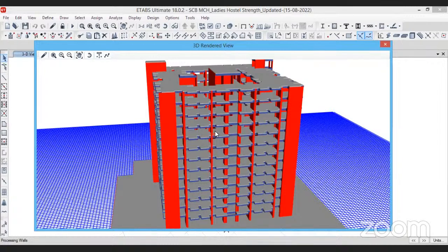Yes, we do. For example, you are watching on your screen, you are using ETABS. ETABS is a structural software where we do the complete design of every member, and after you design every member, you fix your sizes and give the sizes to some other department. Designing will not be done in BIM. Don't you do any manual calculation to design the element? Yes, we do manual calculation, 110%. I personally do manual calculations for every component of the structure.